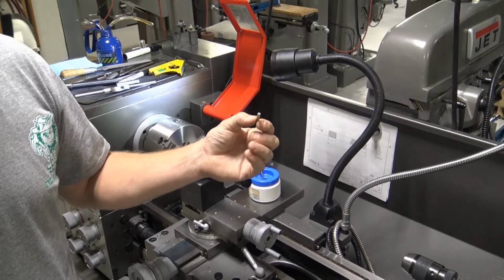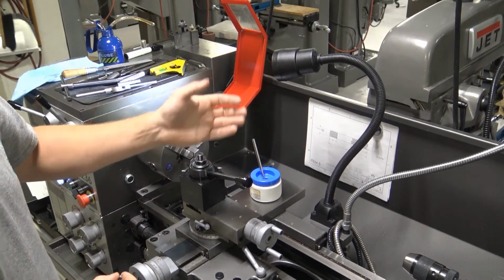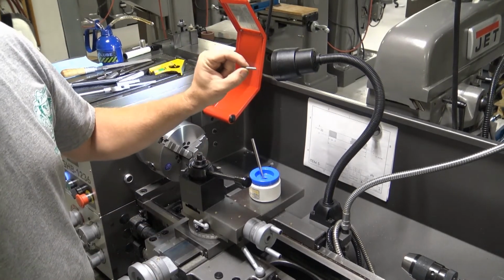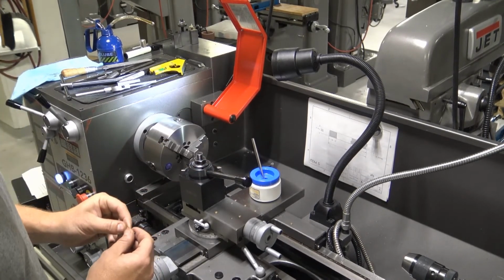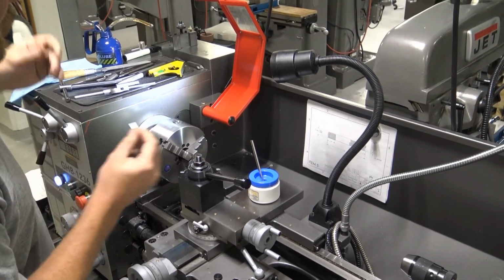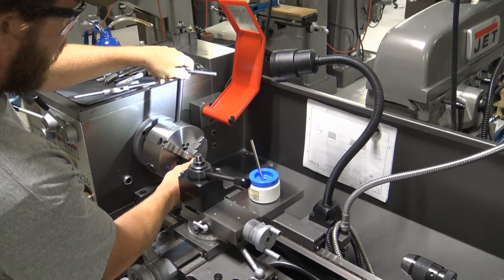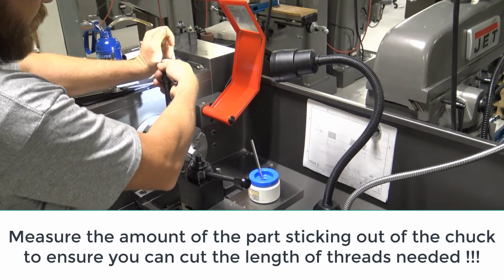Make sure you use the right pin. This one's 1 1/4 inches. All right, don't use your 1 inch one. That's for your crank. So we want to make sure you use the one that's 1 1/4 inches long. Okay, so here's our pin. I've got it chamfered on both edges. All right, what I'll do is I'll just put it in the vise so I don't drop it down in the machine. All right, here it is in the chuck.